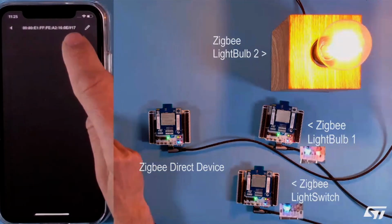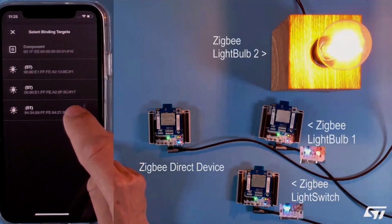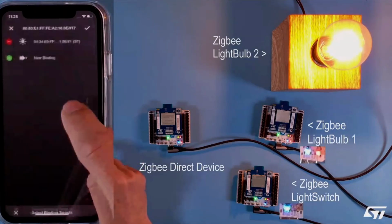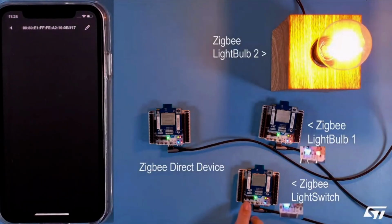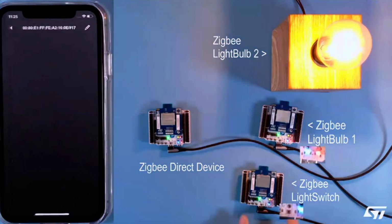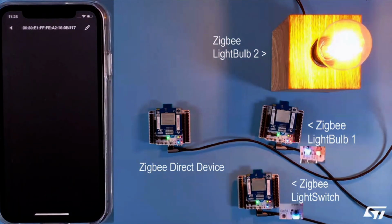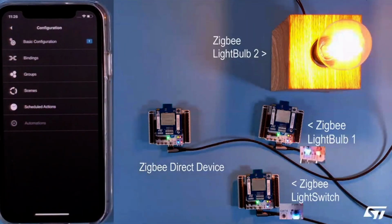So for the light switch, I need to create a binding for the control of the ZigBee devices. So for example, this one. And now I can again control the ZigBee light bulb with the ZigBee light switch made from the Nucleo board. So this is how easy it is to use it. And you don't need any ZigBee hub. It is enough to have one ZigBee board and a Nucleo board, and you can control the ZigBee devices you already have.